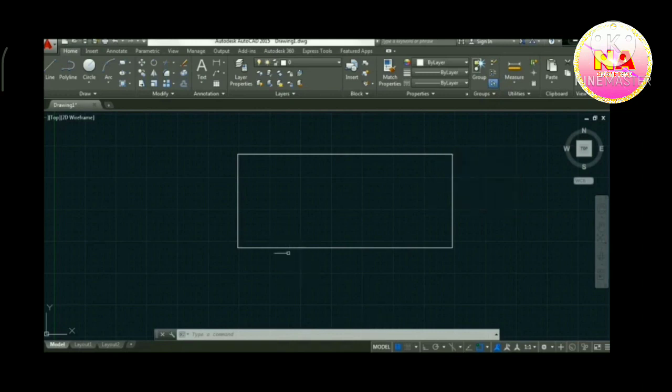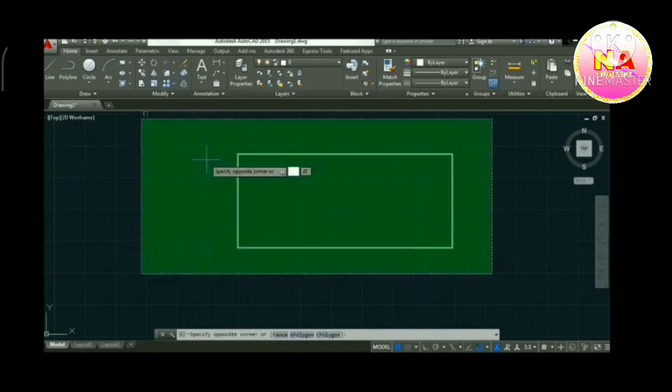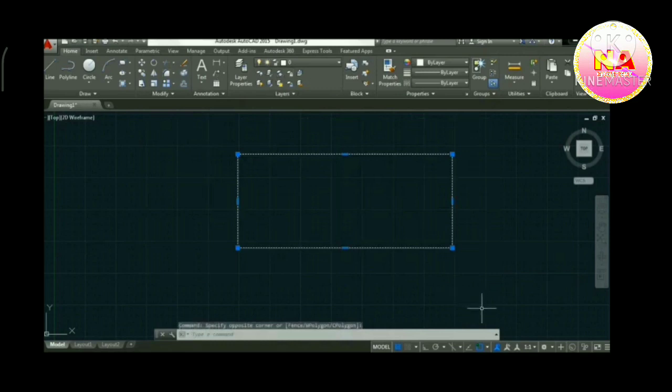Okay, so that's how it's done in AutoCAD. We set first the origin, the lower left corner, and then we set the upper right corner. So now the rectangle of the specified dimension coordinates has been created for us. So let's erase this. I just took it to help you understand as an example.